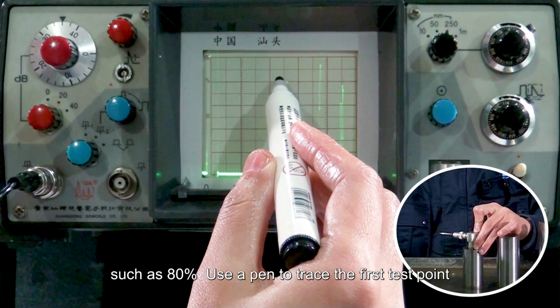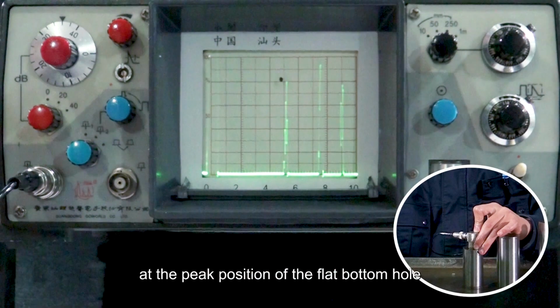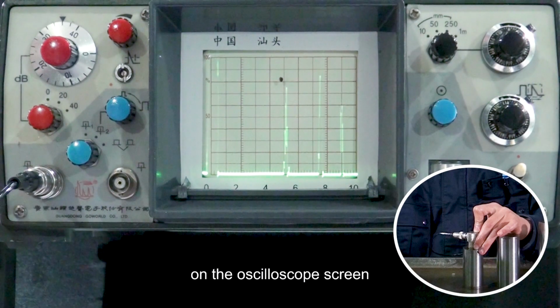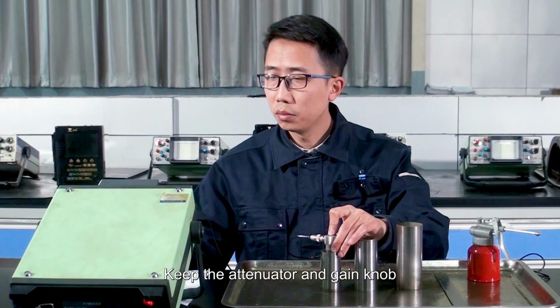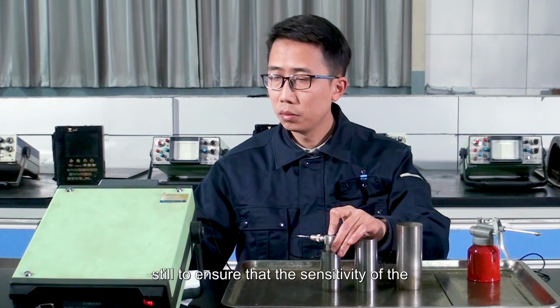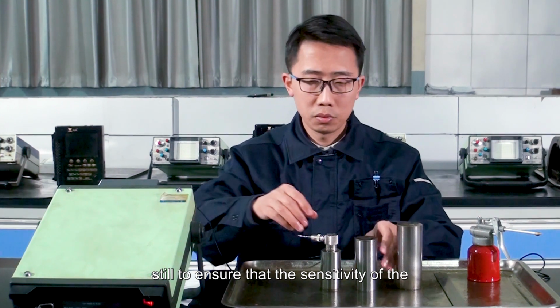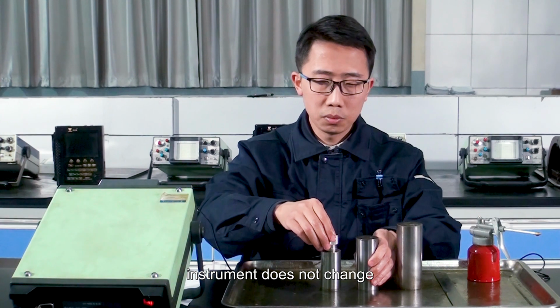Use the pen to trace the first test point at the peak position of the flat bottom hole on the oscilloscope screen. Keep the attenuator and gain knob still to ensure that the sensitivity of the instrument does not change.